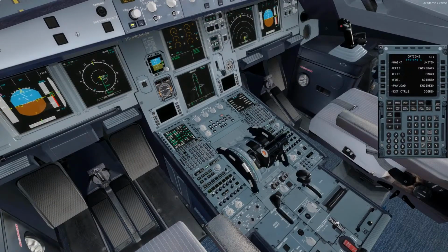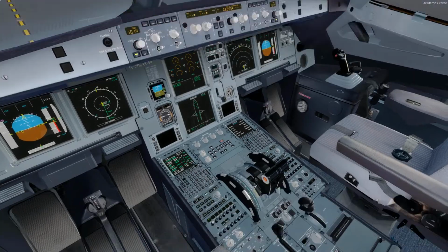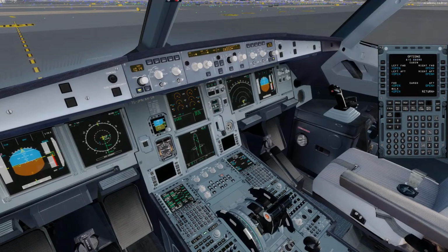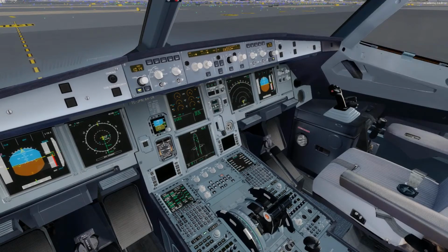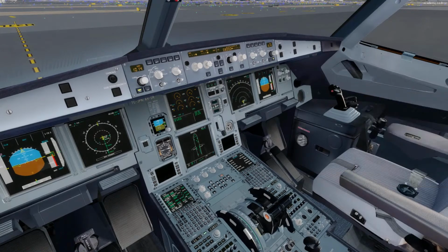And now, as you can hear, we have the clearance for the startup, and I am now free to start the engines. So we'll do the before start checklist below the line, which is anti-skid and nose steering is on because we're not pushing back, and windows and doors are closed. The lock, close the locker here, and let me check the doors again. The doors are closed, and we can also see here that the doors are closed.